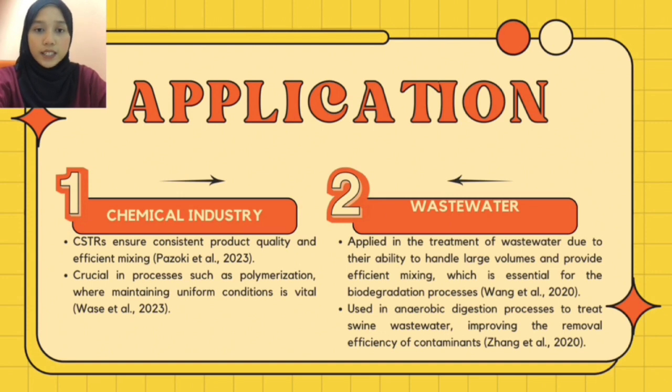So the next one is wastewater treatment. The CSTR has a crucial function in the anaerobic digestion phase, when microbial colonies decompose the organic substances present in the effluent. The utilization of MAP precipitation as a preliminary treatment method facilitates the elimination of ammonia and phosphate from the wastewater, resulting in a decreased burden on the CSTR and enhancing the effectiveness of the subsequent aerobic treatment in the SBR.